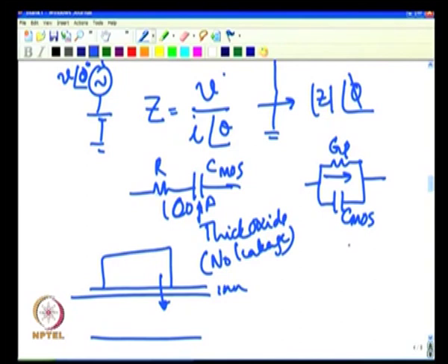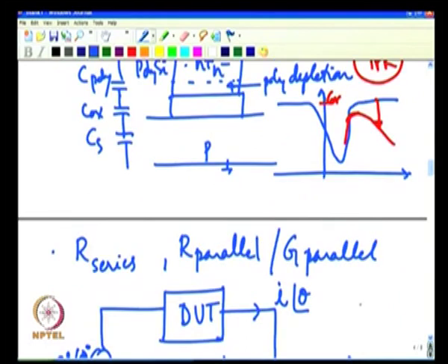On the other hand, if you are dealing with, let us say, less than 1 nanometer of SiO2, or a high K dielectric which is very crappy, you are developing a high K process. Ideally, if you have 5 to 10 nanometers, it should have 0 direct leakage current, but for some reason you really have large leakage, which you can always verify by doing a simple DC IV measurement. Then you better use this model, because there is always a DC conduction path, and what it means is that the current you are measuring has a DC component also.